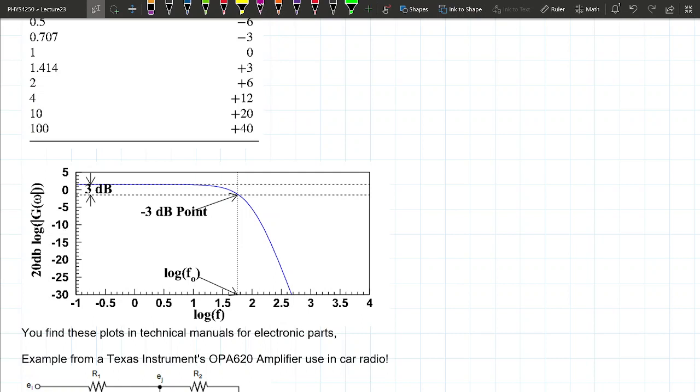But then it goes on and on, and it crosses 0 around here. This is what they call the characteristic frequency. Then you take the log of it, so it turns into some funky number between 1.5 and 1.2, like 1.675 or something like that. Don't think about these numbers too much, but this is how a lot of people look at plots, the Bode plot. You're plotting this funky number versus another funky number that you have to disentangle in your head.